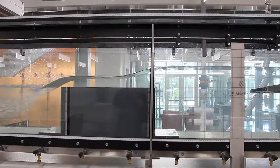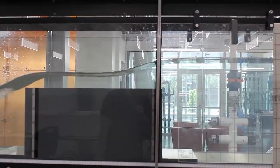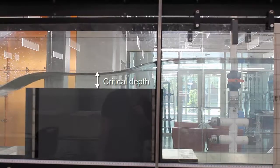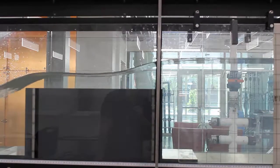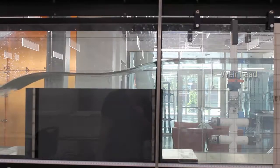As we mentioned earlier, a broad crest weir can be used as a measuring device for the discharge value. To do so, you need to measure the depth of the water above the weir, which gives you the value of the critical depth. Next, to get data for the weir discharge rating curve, you need to measure the water head upstream.